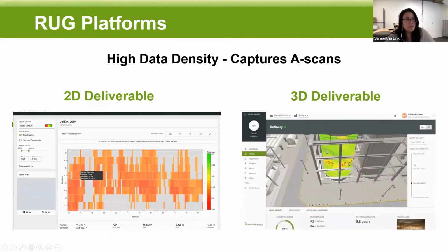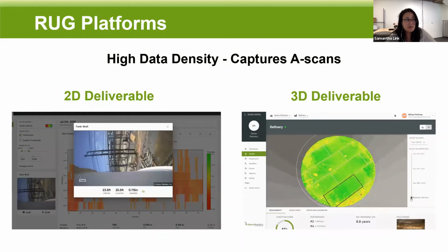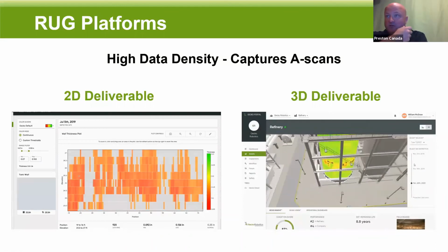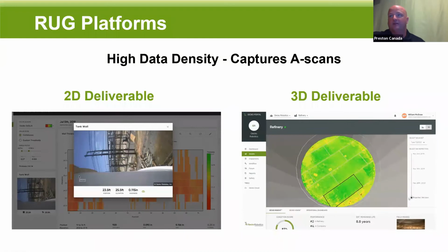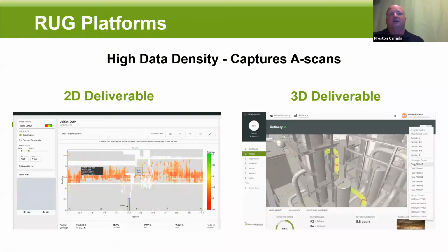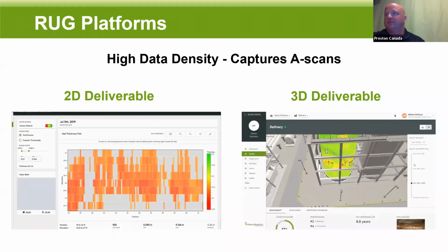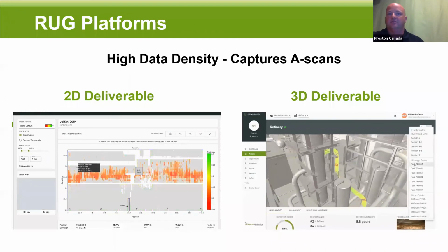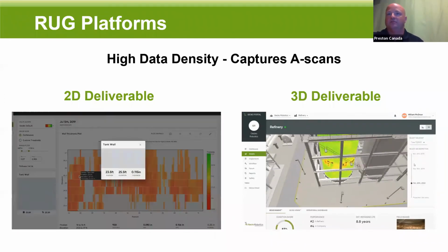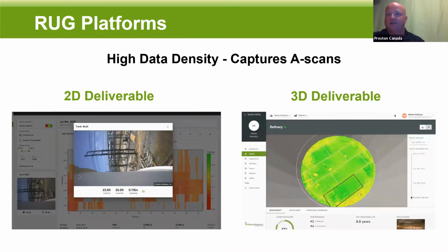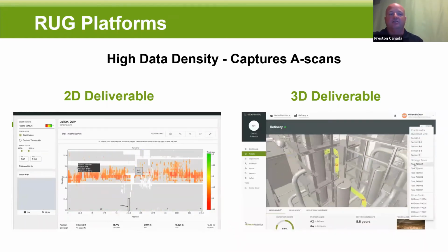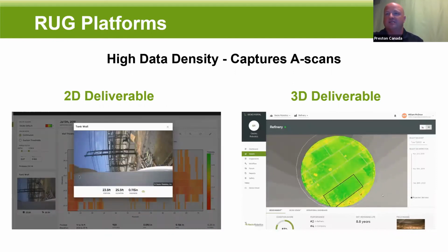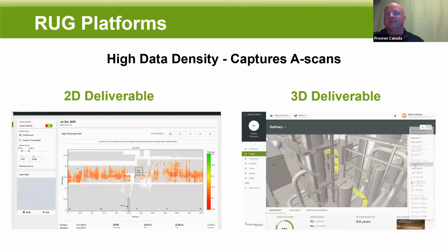And then how do you set up subsequent inspections with these robots so that the inspection data lines up? So we do like to start at the same spots and just help with consistency. So we'll start at the same flange on a piping circuit, or typically at a manway or east, west, north position on a tank. So we'll start in the same positions, but the robots have encoders and systems so the robot knows where it is during the inspection.